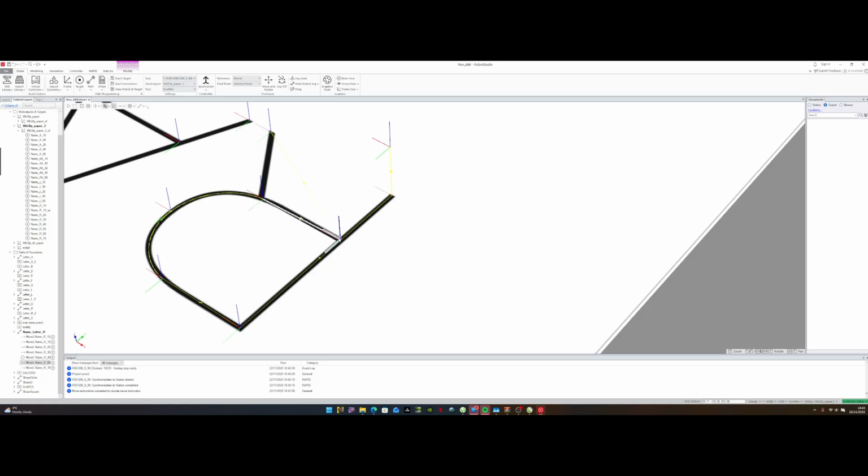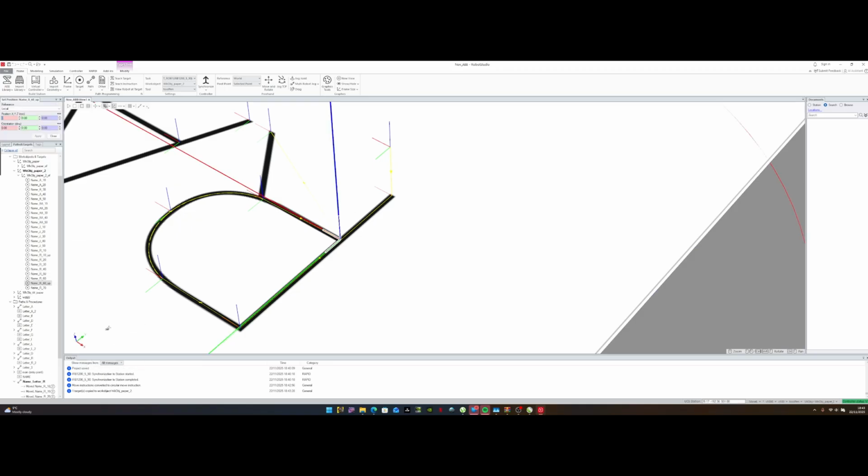And now, how do we get the pen from here over there? Let's add another target. A quick way we can do it is go to target 60. We can right click, you can copy it. Okay, 62. I'm just going to update this to up, right up there. Then I'm going to right click on it and modify target, set position.